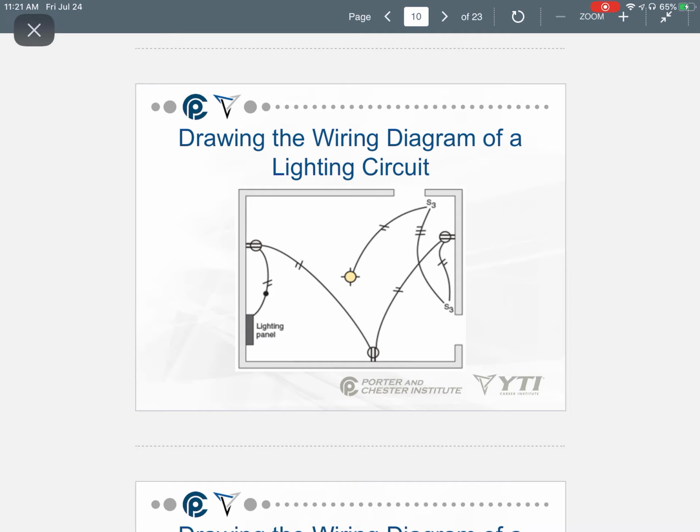You see 3-way switches, but it doesn't click in your mind, oh, I need 3-wire. And so you give them a price on the job. And then later on down the road, after you've already given them the price, you realize, oh no, I need all this 3-wire. That's a big miss on something like that,